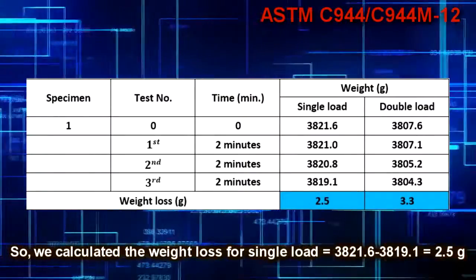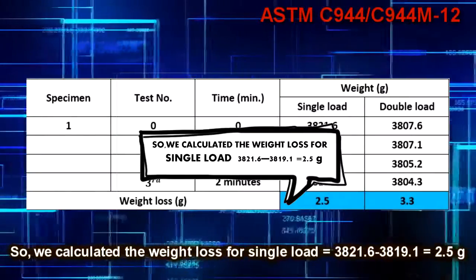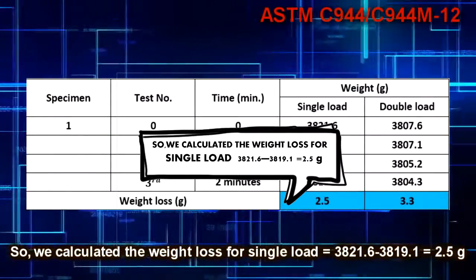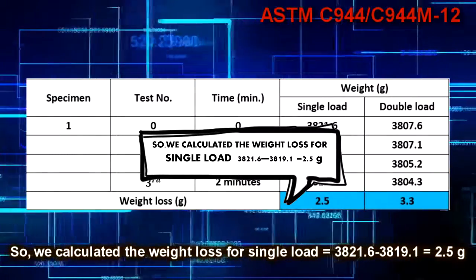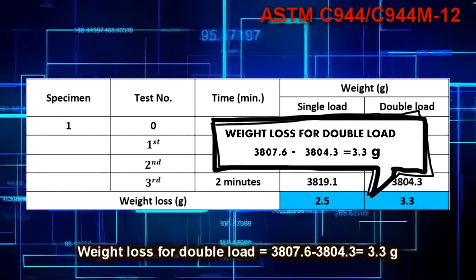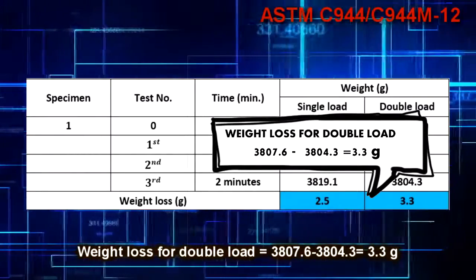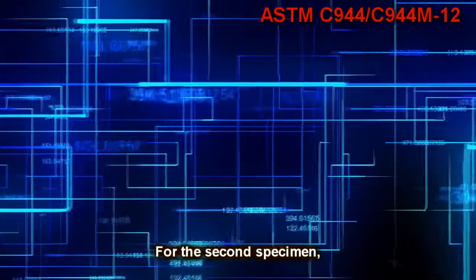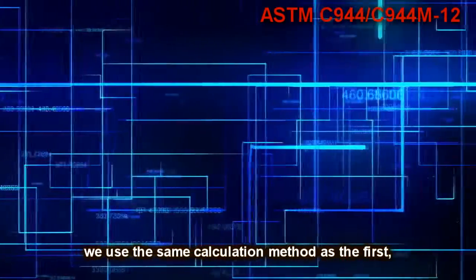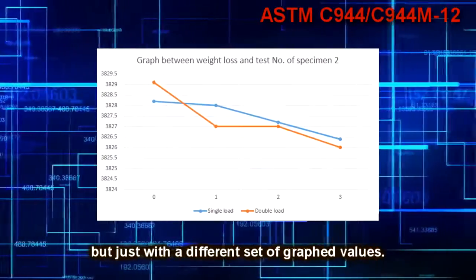So, we calculated the weight loss for single load equals 3,821.6 minus 3,819.1 equals 2.5 gram. Weight loss for double load equals 3,807.6 minus 3,804.3 equals 3.3 grams. For the second specimen, we use the same calculation method as the first, but just with a different set of graphed values.